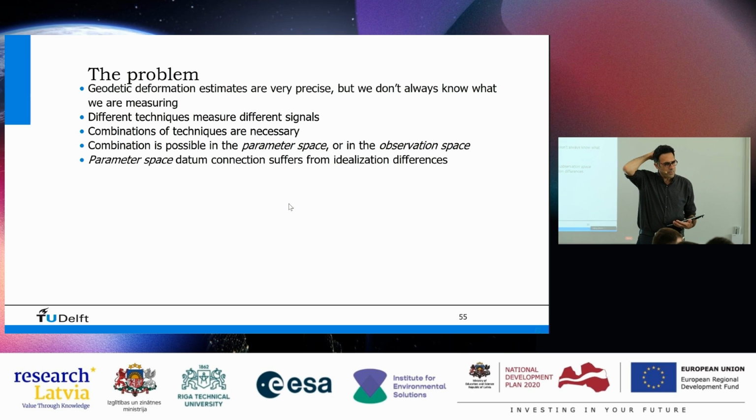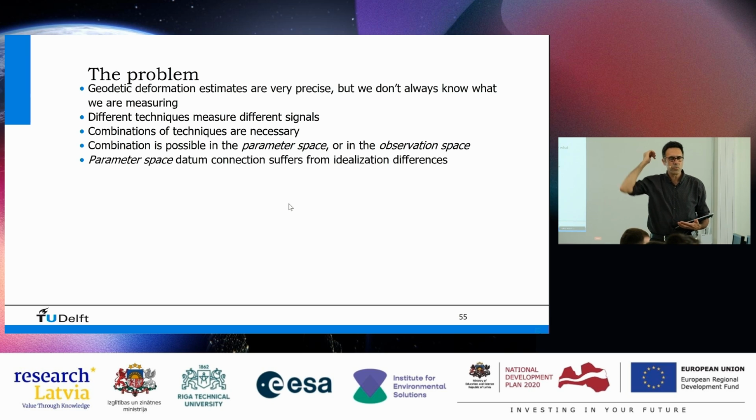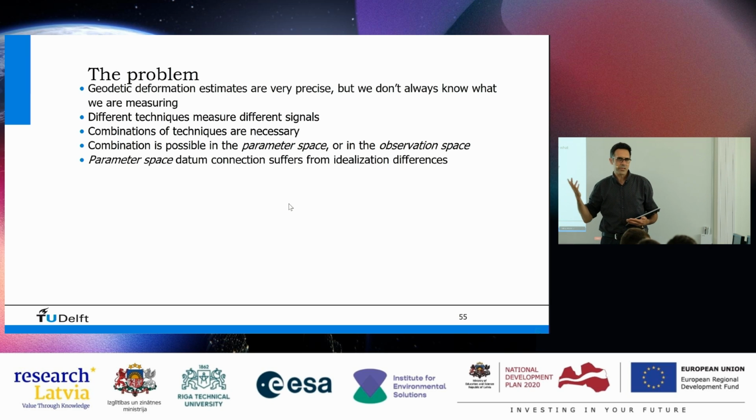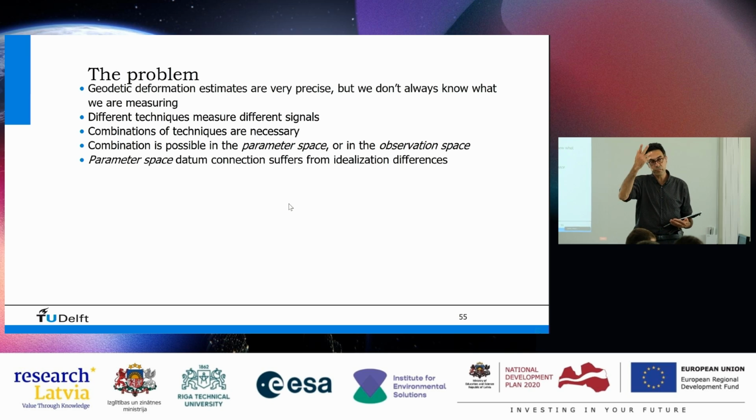Also there, in the past, when InSAR started, there have been many studies where the InSAR results had to be validated. People didn't really trust it. It was new. So they said, okay, let's compare it with leveling. There are hundreds of comparisons with leveling, with GPS, any other techniques. And the problem there is that it was never a perfect match. There was always a difference. That is partly because these different techniques measure really different things. Measurement bolts in a wall are something else than a reflection from a roof.